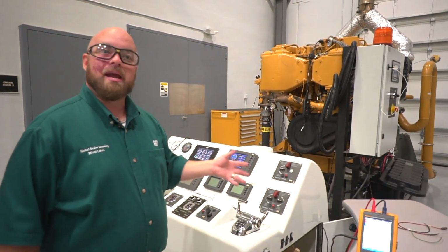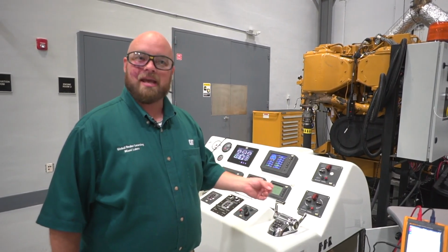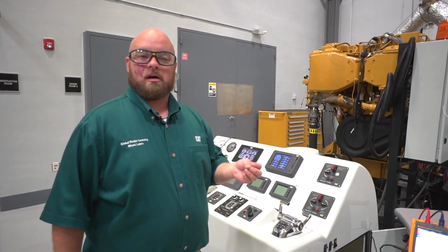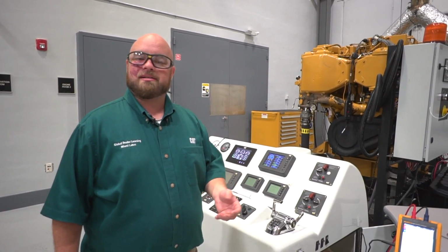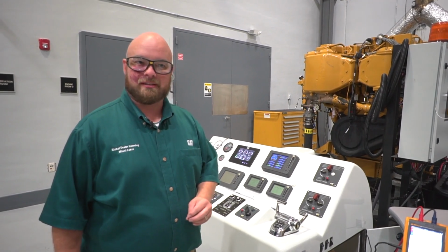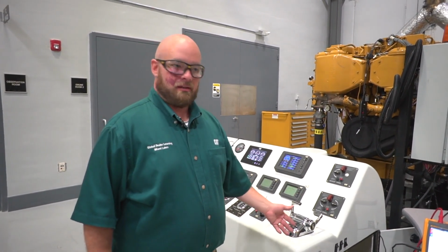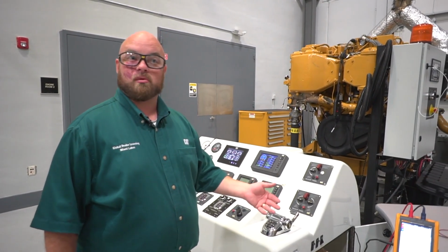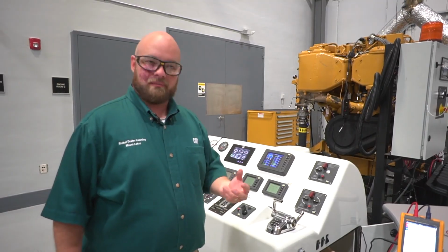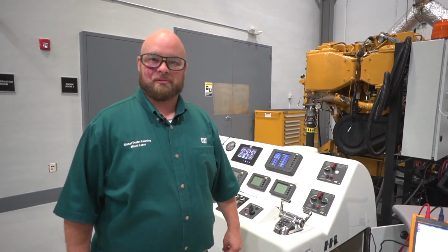So this may or may not cause some problems in the future for us if we have the CAN negative shorted to ground. It's definitely not what we want, but when you hear that CAN is a very, very robust system and it can tolerate a lot of different faults and noise, this is an example of that. Robust system to where the CAN negative shorted to ground, everybody's actually still communicating. So some faults like this, CAN holds up pretty well to.